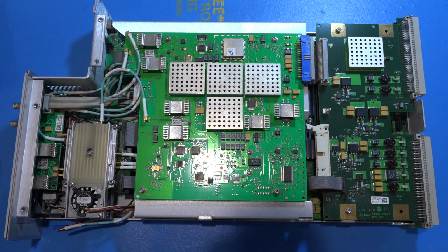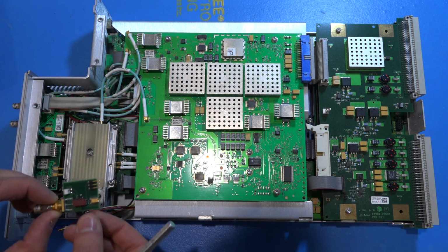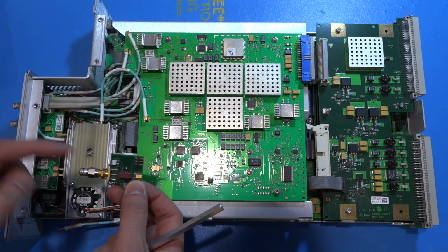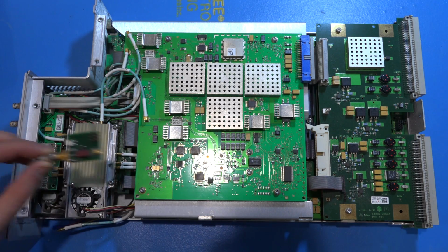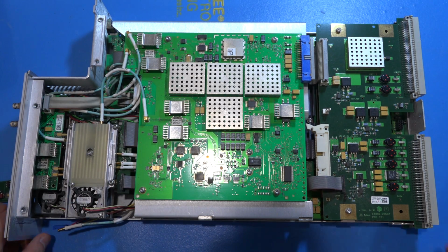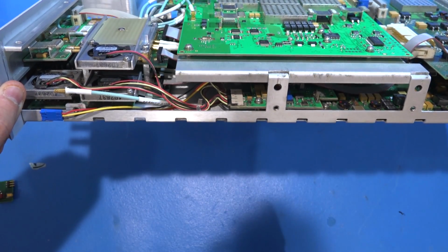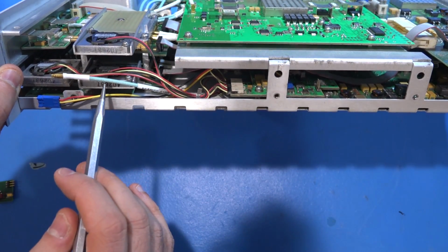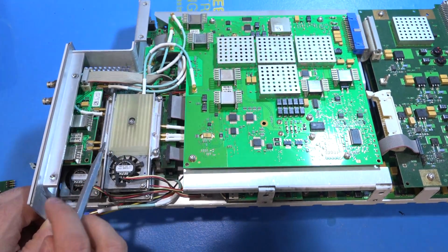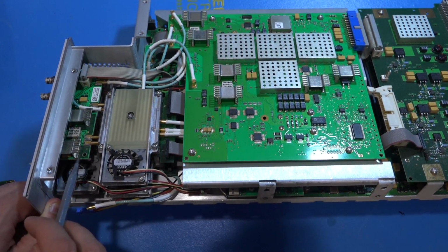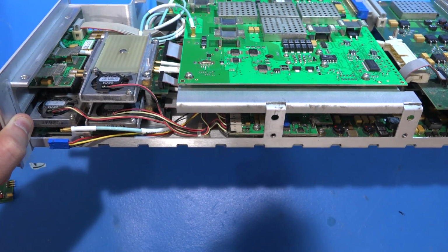So what is actually going on here? Well, I took out this module, and this module is what the control delay input in the front right over here is actually connected to. And this doesn't have a lot of interfaces on it, so I want to talk about that a little bit. Now let me tilt this a little bit as well to show you what's going on. So at the top we have the clock generator, and at the bottom we have the actual data generation, and these are connected with GPPO I/O connectors to the front-end amplifiers, and there's multiple stacks of those as well, and they all need to be thermally cooled.